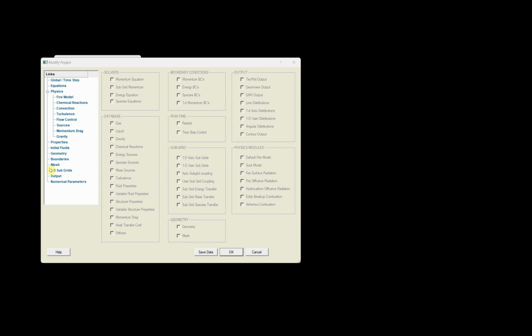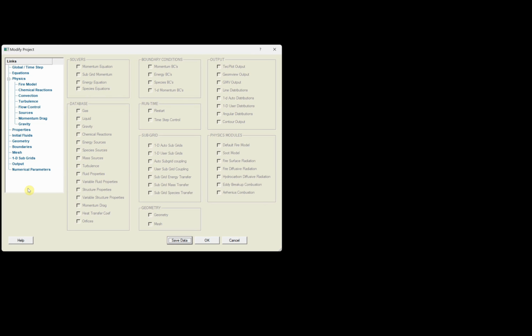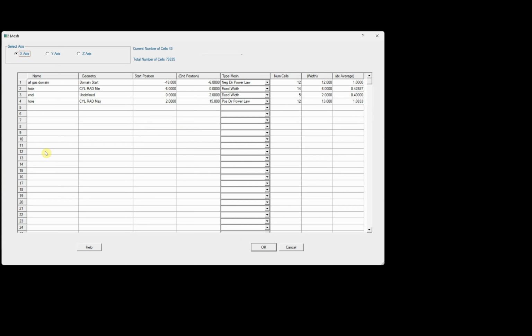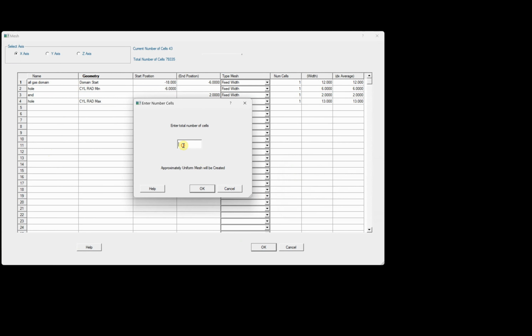Okay, now the next step is to create a mesh. So I'll click on mesh, and we have to do it in all three directions, X, Y, and Z. This was the default that it came in with, but the best way to do it is to allow the code to scan the geometry and find points that are relevant that you want to map to. So now that we know where to insert points in our meshing, we'll go into mesh. We'll scan the geometry like always. We'll use 50 points.